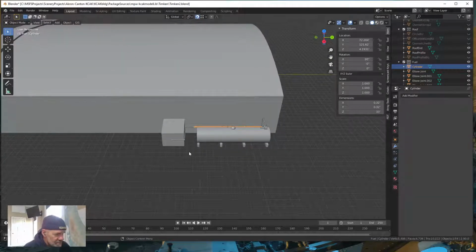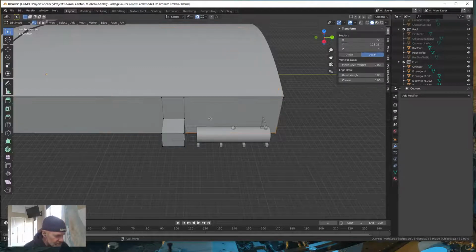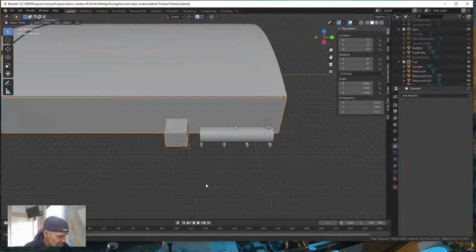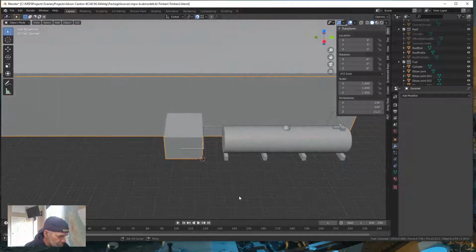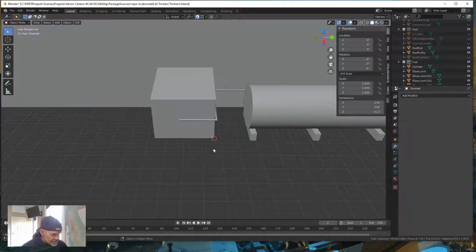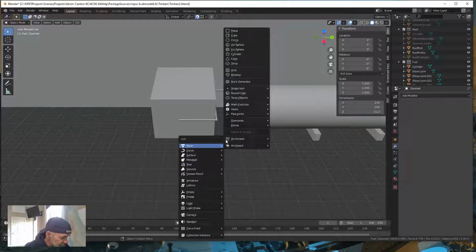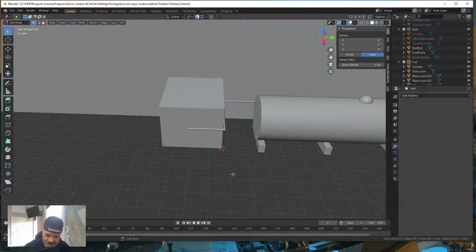Okay, so let's select this. Select our Quonset, go into edit mode, select this corner vertice, and Shift S and move our cursor to that point, get out of edit mode, and then zoom into this area. At this point right here, I'm going to Shift A and add a vertice, mesh, single vert, add vertice. So there I got a vertex right there.